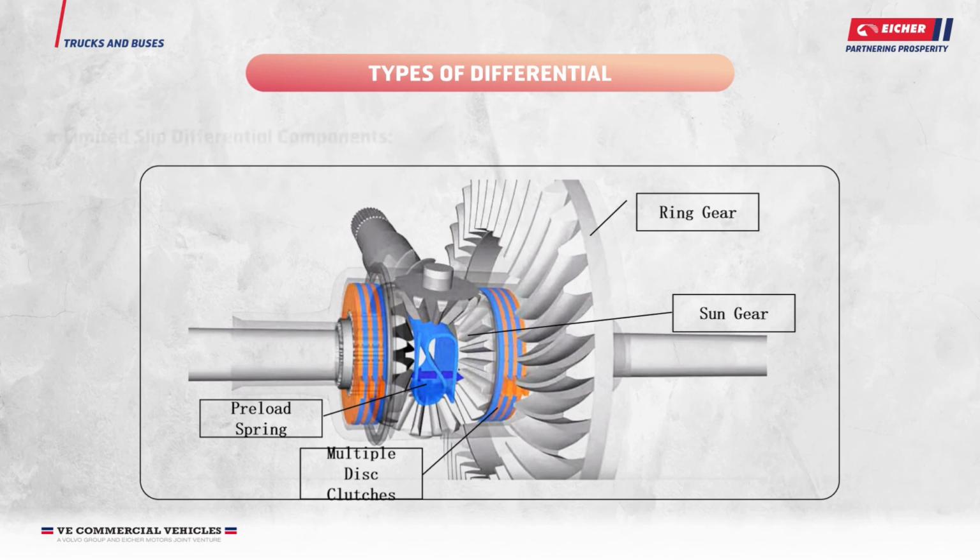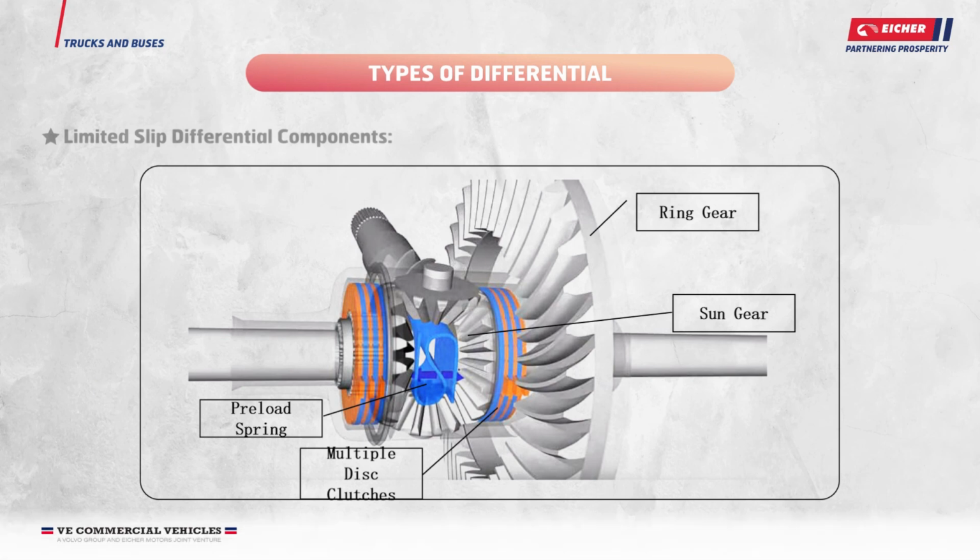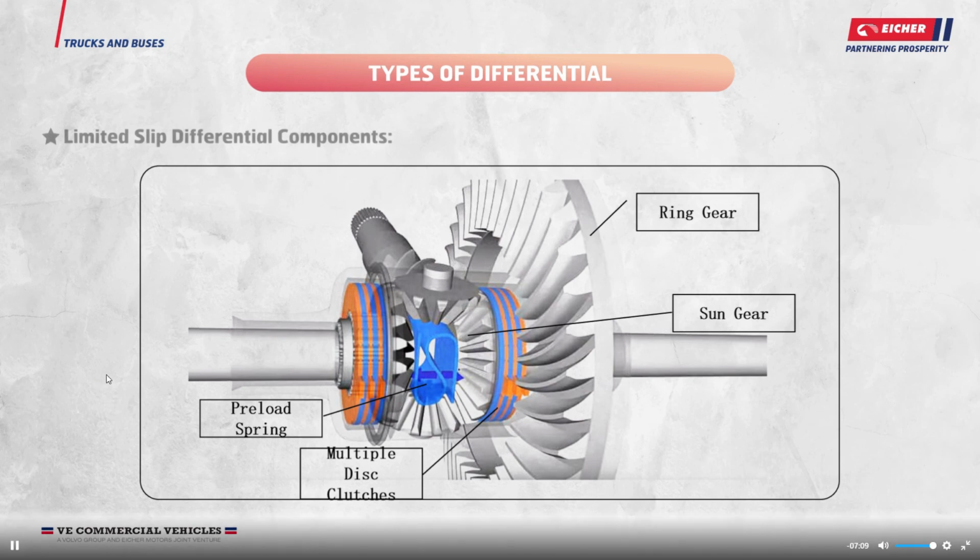Space between the side gears is fitted with a preload spring. The preload spring will always give a thrust force and will press the clutch pack together. The bevel gears have some speciality. When torque is transmitted through a bevel gear, axial forces are also induced apart from the tangential force. The axial force tries to separate out the gears. So, during high torque transmission through the spider and side gear arrangement, a high separating thrust force is also transmitted to the clutch pack. This force presses and locks the clutch pack assembly against the wall of the casing.